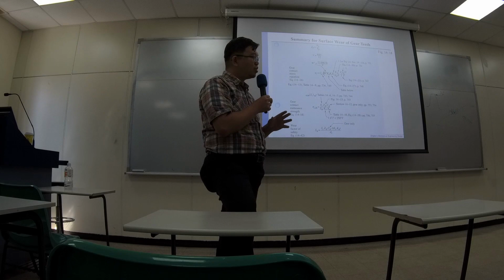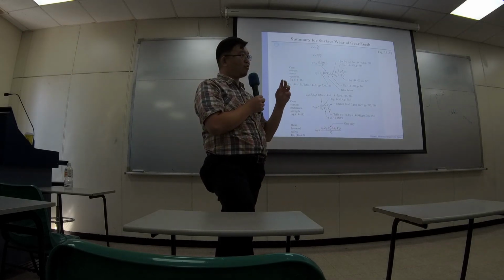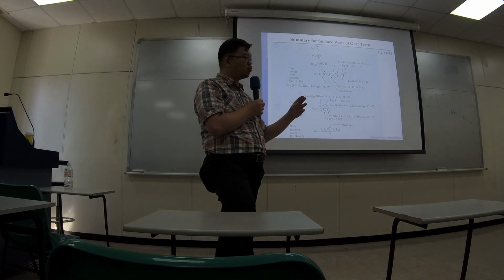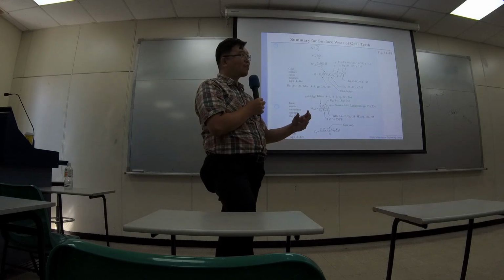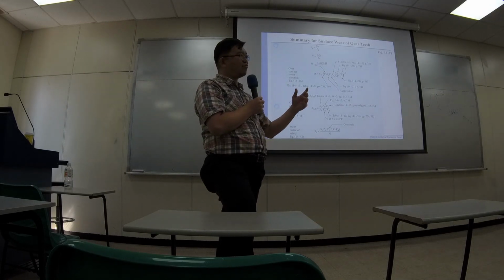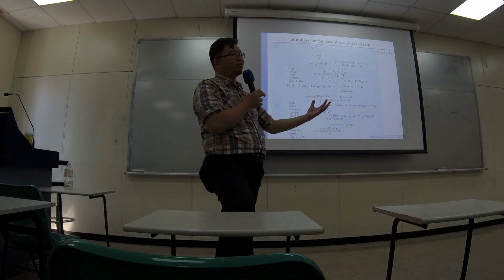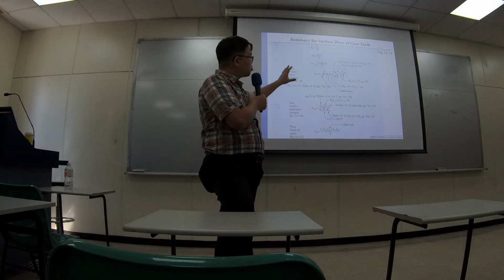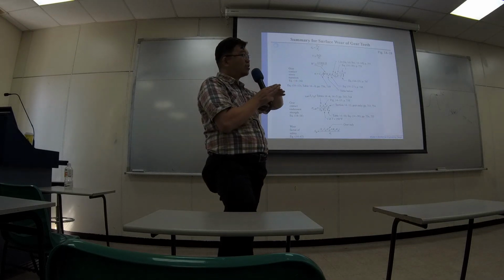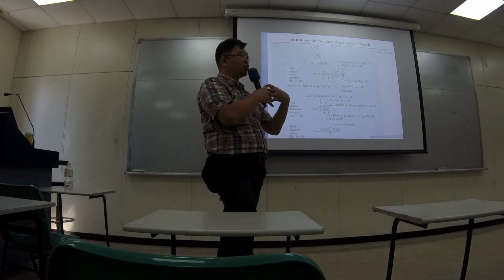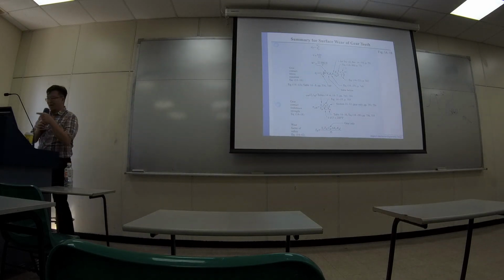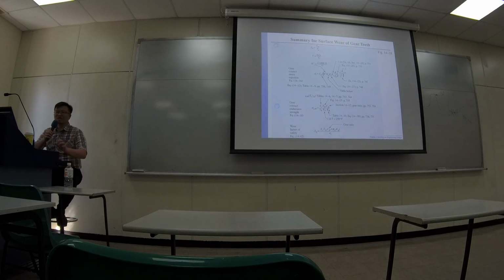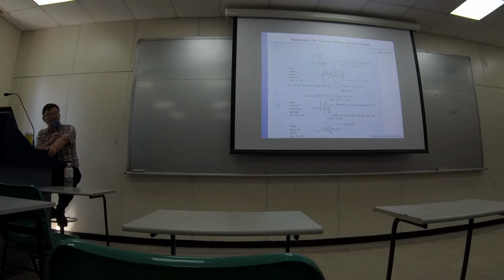However, I need you to know, in the future, when you are designing a gear, if you are truly trying to choose a gear and study how long this gear is going to last, you cannot just treat it like a cantilever and just make sure if it's going to break or not. You also need to think about the wear at the surface. Because if you have surface wear on the teeth, then you don't have a smooth connection with the opposite gear. Okay? So I recommend you come back to this book in the future when you are designing gears. Okay?